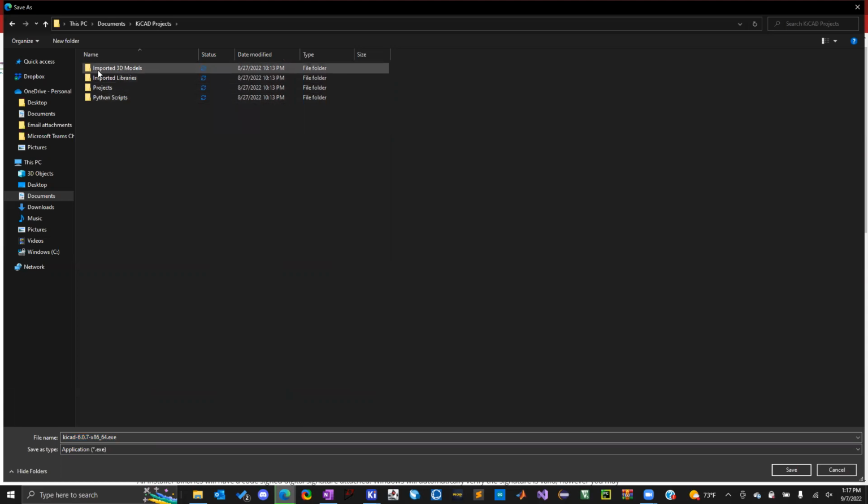So the first thing is you may be interested in importing 3D models that you find online to put on your circuit board so you can see what it would look like with all the components. It really helps to make sure that none of your components are overlapping with each other, that you can actually physically fit them on the board. The imported libraries are really important. That's what's going to give us all our symbols and our footprints, which I'll talk about a little bit later. We'll get into symbols, but we're not going to talk too much about footprints until next Wednesday.